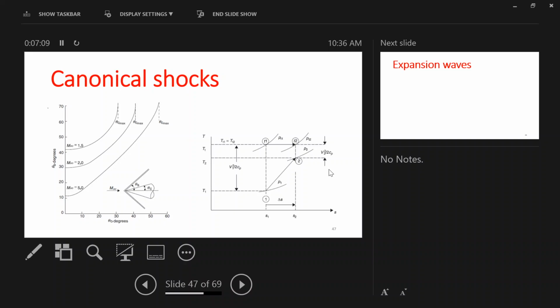Theta doesn't go to infinity. That doesn't really make any sense for theta. That's for 0 to 360 degrees, right? So what does that mean? What's going to happen? Because we can definitely construct a cone that has a higher cone width, and that can definitely be put in a supersonic condition. So what's going to happen to that cone in that flow? Well, I know in an oblique shock, I assume it's somewhat similar. If you increase the angle of the wedge and it's greater than the deflection angle of the possible wave, it becomes detached. Exactly.